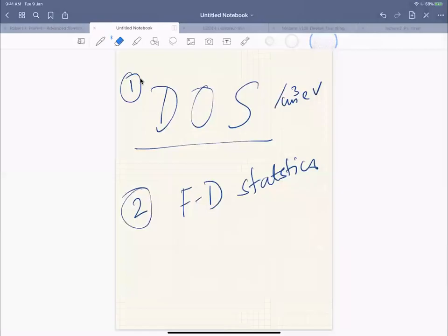How many chairs in the classroom is nothing but the density of states: how many energy states are available. If there are 40 chairs, then the maximum number of students that could be in that room is 40. That's why density of states is a very important parameter for the carrier concentration. The higher the density of states, the higher the electron and hole concentration will be.